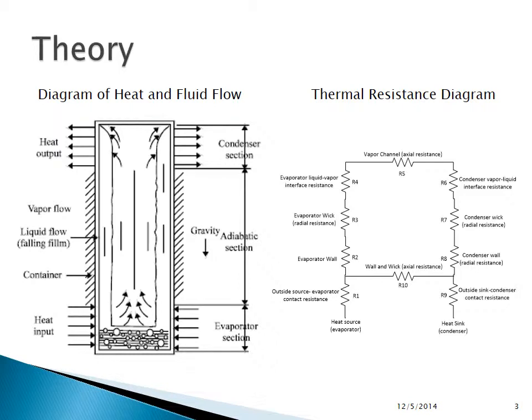The theory behind the heat pipe can be demonstrated in the diagram on the left. The evaporator section, located at the bottom, is submerged into a hot fluid. From there, the fluid on the inside of the heat pipe is heated to a boiling point. The steam then rises through the adiabatic section into the condenser region, where the fluid is then cooled and gravity takes it back to the evaporator section. As long as heat is being input to the evaporator, this will be a constant process.